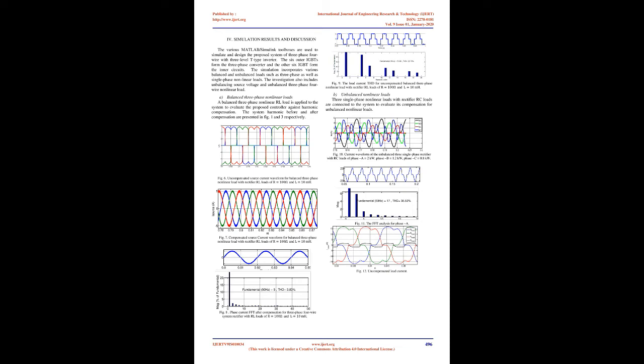The basic block is formed from the feedback a delay of n sampling periods, where n equals T/Ts, T is the period of the signal to be tracked or rejected, and Ts is the sampling period.